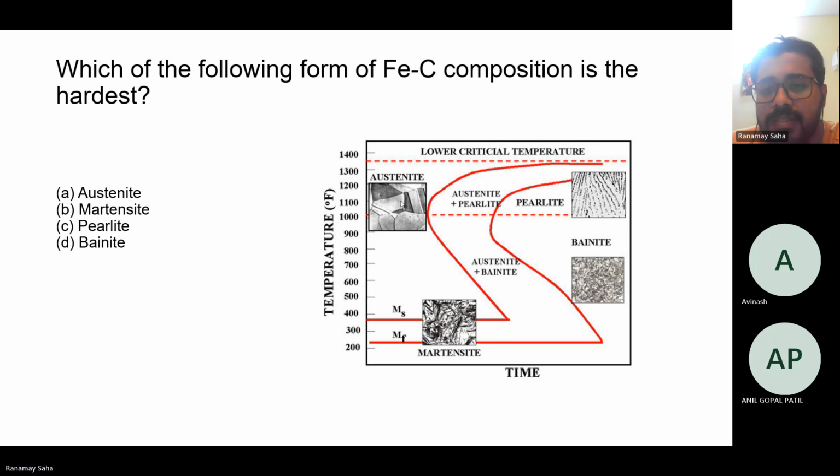forming, right? Similarly, if you rapidly cool down austenite to this particular temperature range, this is, by the way, called quenching, a rapid cooling process, and martensite is formed. Because you have carried out rapid cooling, the grains don't get enough time to relax and recrystallize.